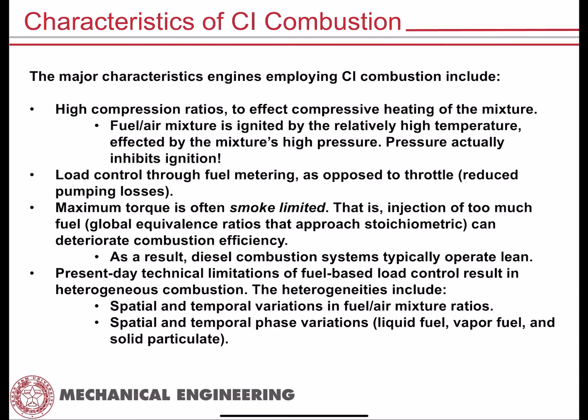They're relying on high compression ratios to basically ignite the mixture, right? So they generally have high compression ratios. That would contrast, for example, to spark ignition engines, where, as we talked about at the end of the semester, really the last thing we talked about last semester, spark ignition engines are actually limited on their compression ratio because you start to run into something called fuel knock. Well, compression ignition engines are relying on that compression for ignition. And so you want that compression ratio to be as high as possible.